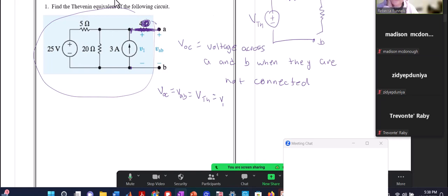So when I see that I have a voltage source and a resistor in series, and if I do source transformation and change them to a current source and a resistor in parallel, then I've got everything in parallel. And with everything in parallel, whatever voltage I get, that's my answer to the problem. So that's really handy.